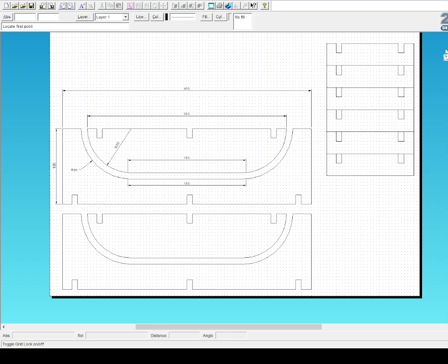So I'm going to switch off my grid lock and switch on my attach. Attach will attach from one corner to another, and there we go, we've got a 9 measurement. Now we'll get to those in a moment. I'm also going to take a measurement off of these using my grid lock. Oops. Hang on, if you run into difficulty, just press escape and reselect the tool, just as I've done there. Okay, great. 140 by, I think that's 35.